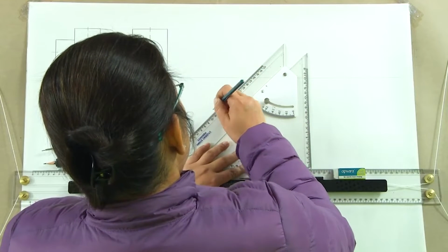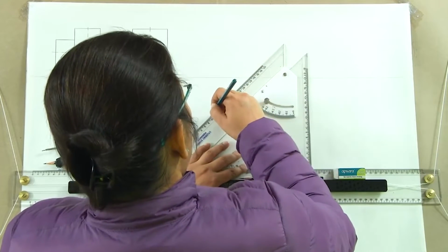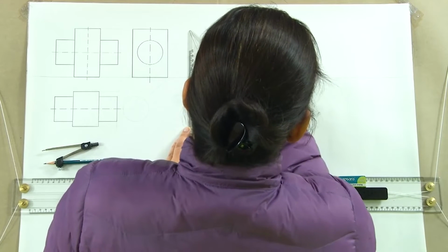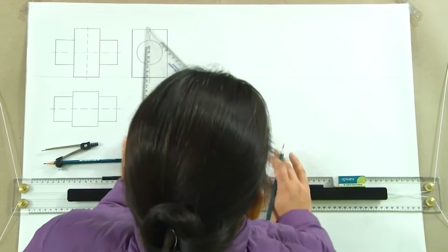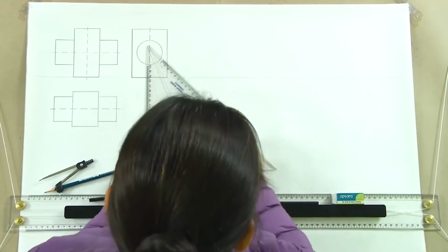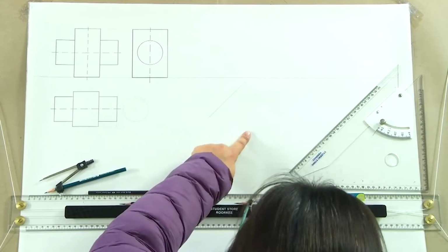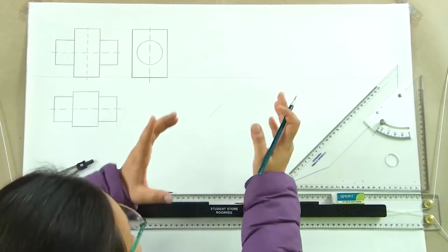So, what we will do, we will start with, say, the square prism. The square prism is assumed to be kept diagonally to the VP. So, the axis is perpendicular to HP, parallel to VP, and the base is put diagonally. We will make that first drawing first. Let us assume that it is a 10 centimeter square prism which is kept diagonally. So, this is what the square base is going to be, and it is kept vertically. So, we see it like this.